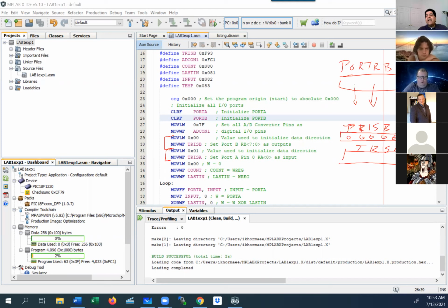It's like a hub and spoke, like a train station where everybody has to come in and go out of the same spot. If you want to go someplace, you have to go to the central station before you get to go someplace else. If you want to move things from place to place, a lot of the time you're forced to go through the W register because they're not connected to each other. So the W register changes all the time. Okay, so you're constantly giving it new values, using it, and pulling from it to do other functions. Okay, that makes a lot of sense.